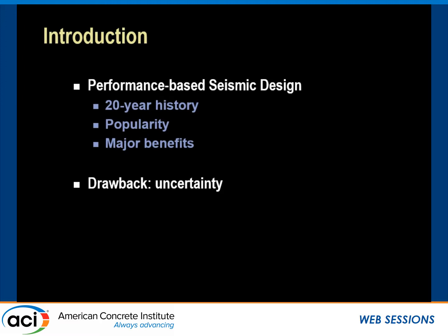It has a lot of major benefits. The elimination of structural height limits, the elimination of the backup moment frame, and of course better understanding of building behavior. But it has one really big drawback, and that is the uncertainty associated with predicting the MCE results from the linear code checks and from the SLE check.